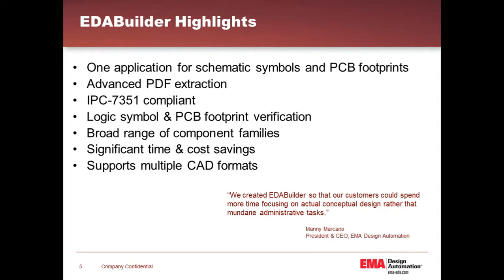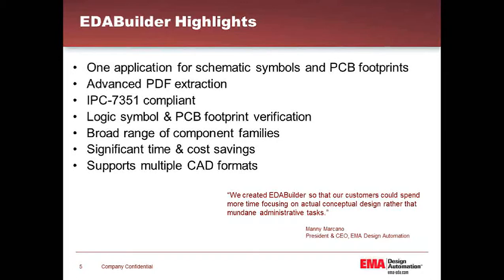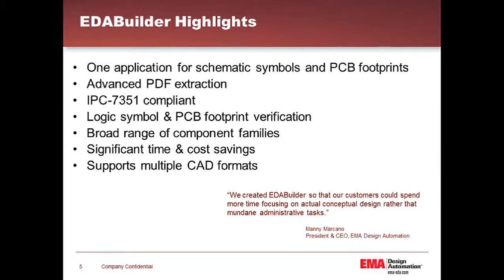So the footprint generator uses mathematical equations to calculate the land pattern dimensions and the pad stack sizes. And again, this would be to generate IPC 7351 compliant parts. EDABuilder actually ships with many common package calculators, or what you might consider to be a template, so that you can choose the particular package style you want, and then you'll be presented with forms that allow you to add the dimensions to those forms according to that part.